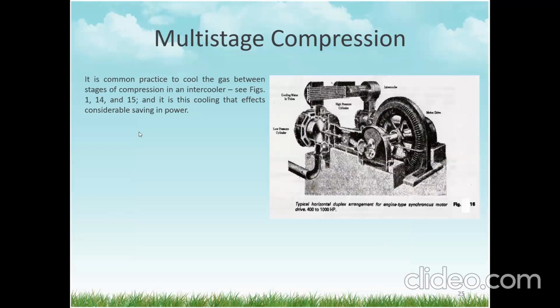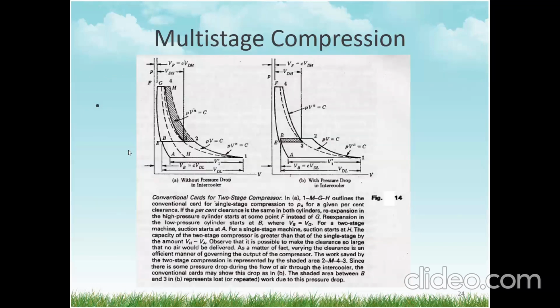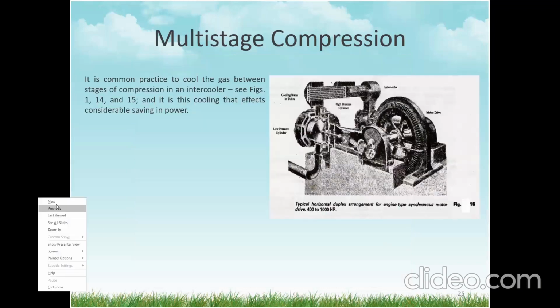It is common practice to cool the gas between stages of compression in an intercooler. This is the intercooler, in figures 1, 14, and 15. And it is this cooling that affects considerable saving in power. So this again is a two-stage.